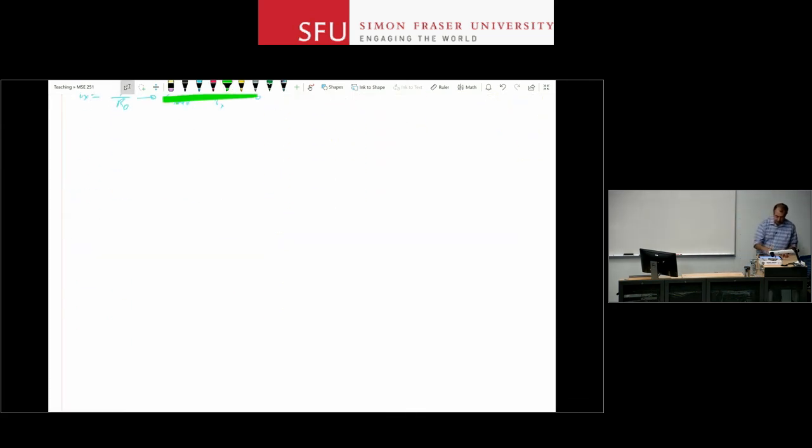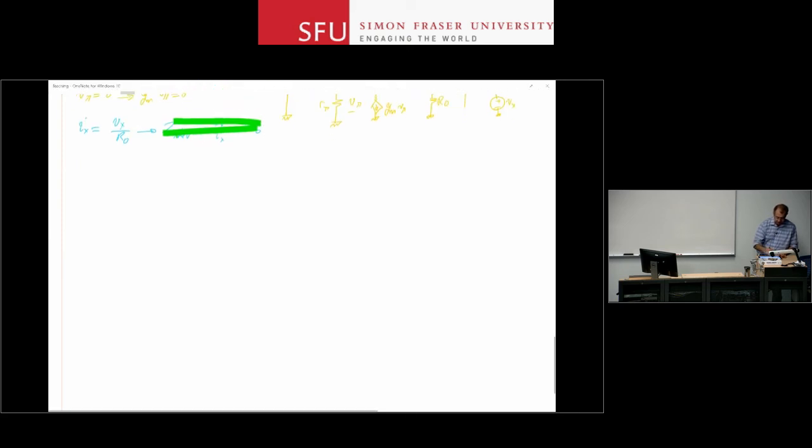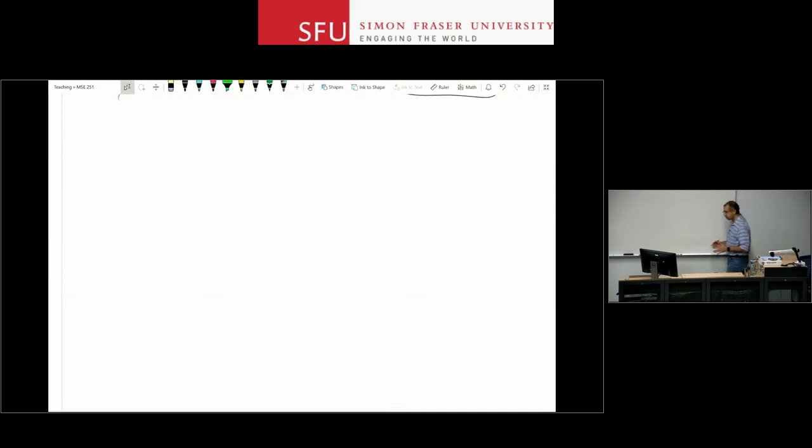Now, the last circuit theorem or technique that we want to quickly overview here is superposition. Again, it's a technique that you use to analyze linear circuits, and superposition basically means that if you have two independent sources applied at the same time to the circuit, you look at the output due to one of them while the other one is taken out, calculate the output, then insert the second one, take the first one out, calculate the output, and the true output when both of them are attached to the circuit is the sum of the two.